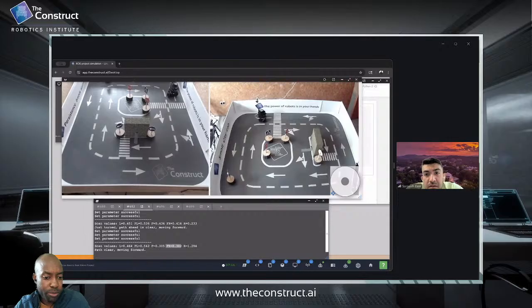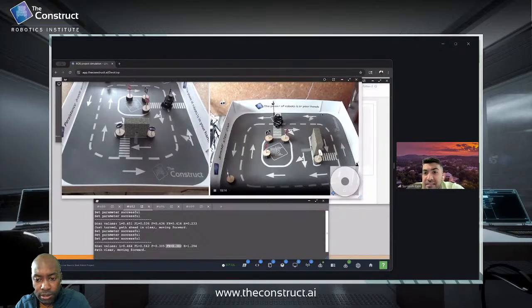With regards to the threshold value, are you taking 0.3 for every laser index that your robot is receiving? Like if the robot is moving forward, there's front left, there's front, and then there's front right. Are you checking that all of those three satisfy the condition of being above 0.3 for it to move, or is it just one or two? How are you doing it? No, I consider all of them, because if you consider just the forward of 0.3, or the front right, for example, at some points it's going this way, and it can be close to here.